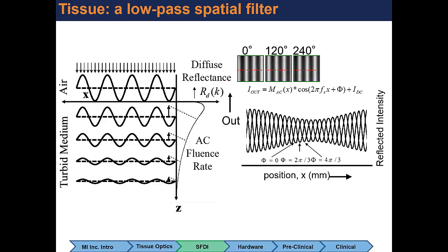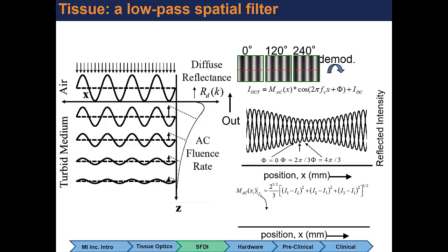And then what we want to capture is this envelope function. You can kind of see it forming in your eye, but it's very simple to calculate the amplitude of that AC wave independently from the DC wave that's also being projected at any given time. You see that there's always a DC offset here and then an AC wave riding on top of it. Light can't be negative, so you're always going from 0 to 1 coming in and less than 1 coming out.